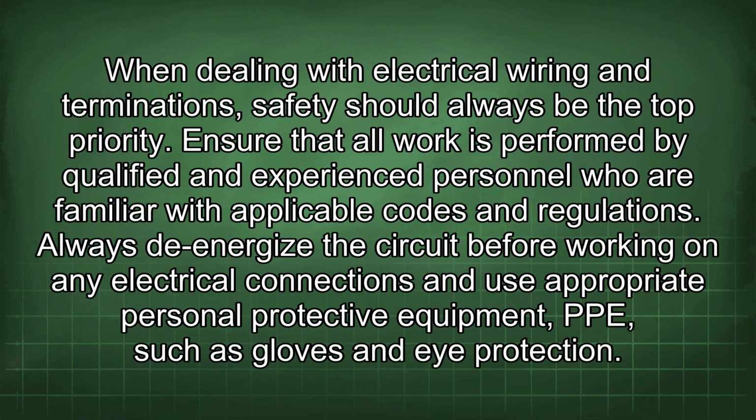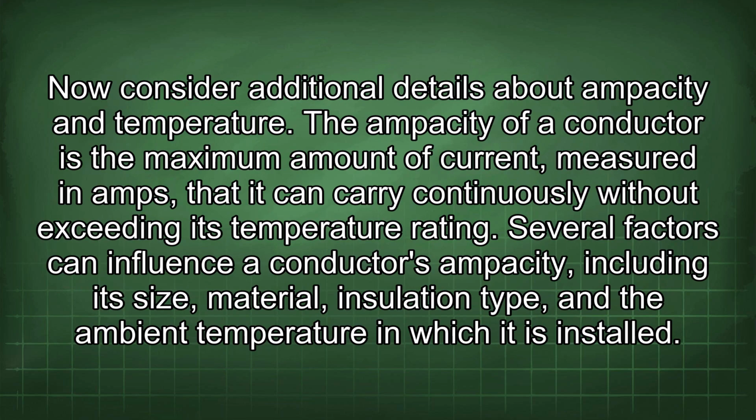When dealing with electrical wiring and terminations, safety should always be the top priority. Ensure that all work is performed by qualified and experienced personnel who are familiar with applicable codes and regulations. Always de-energize the circuit before working on any electrical connections and use appropriate personal protective equipment (PPE) such as gloves and eye protection. Now consider additional details about ampacity and temperature.